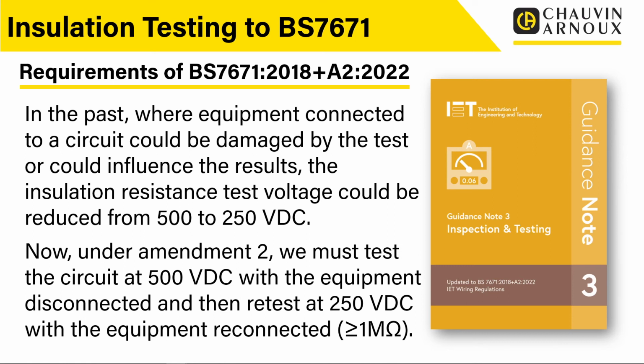Where I think this does call into question how this will get interpreted in the real world is when we're doing things like electrical installation condition reports, where we're testing installations, particularly complex installations, where there is already equipment in service, and it's almost impossible to go around and take every piece of equipment out of a circuit. One example that always used to be talked about with this is if you've got a socket circuit with surge protected sockets, so they've actually got surge protection built in.